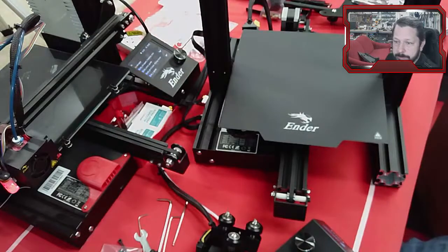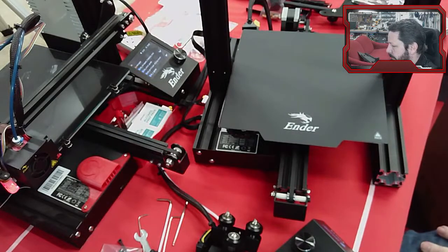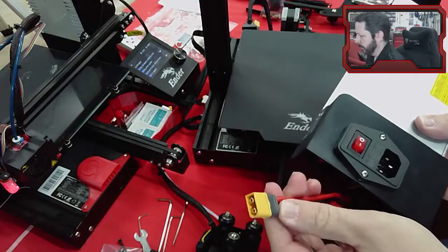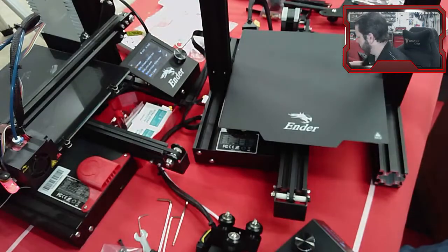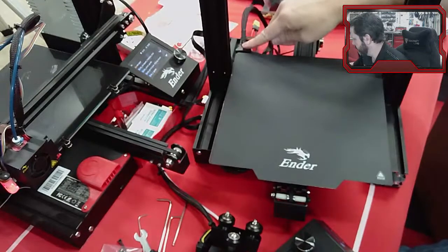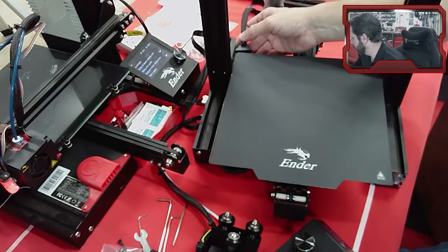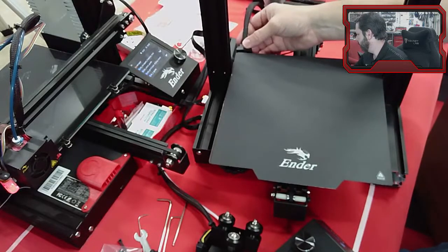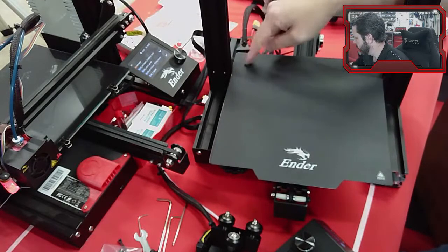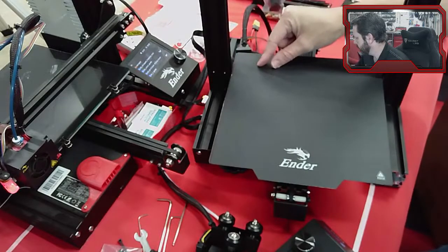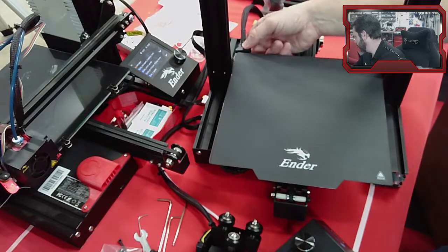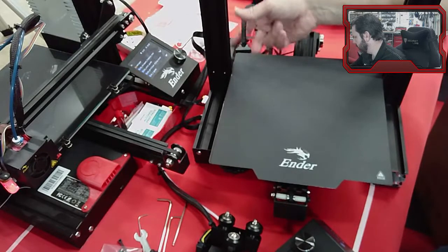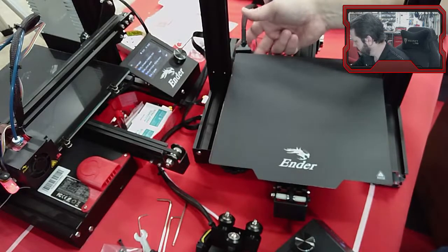Anytime that I've seen one of these printers have a fire hazard problem, it was this connector. What happens, either that or a bed connector back here. This one is a little bit loose, so I'm going to have to work on that. I don't want that loose. I don't know why it's so loose. But the power going into the bed is just soldered onto the bed underneath here, and this strain relief is a little bit loose. I think it has to do with the way they've got the bed tightened down. I'll have to check it.